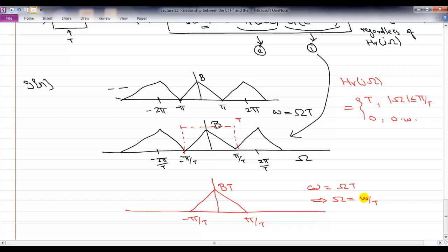Okay? It's almost the reverse of what we saw when we were going from continuous to discrete, except that you have this reconstruction filter that you have to account for. Okay? And if this G[n], if you go back to our previous cases, was really obtained from a continuous time signal, then in that case this new signal G hat of A of t will be exactly the same as what you started with.